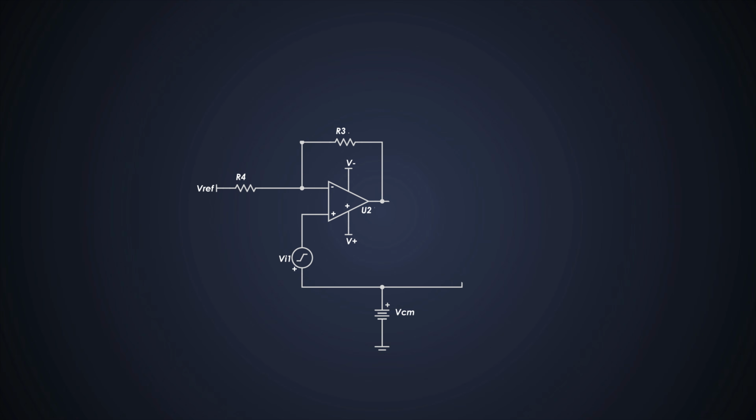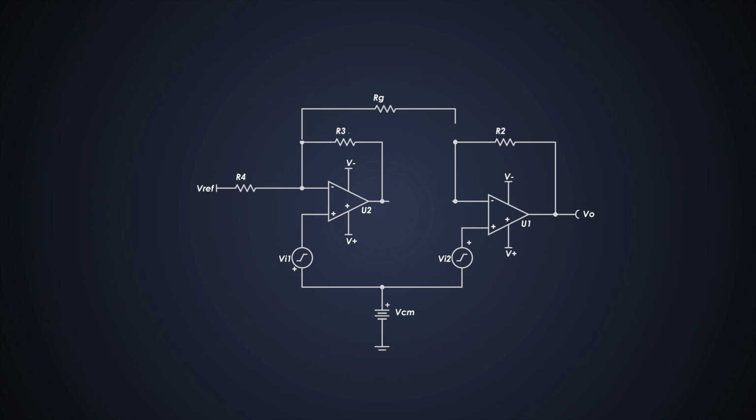It is made up of a non-inverting amplifier and a differential amplifier with negative feedbacks. Apart from that, we'll use one more feedback from the input of the second op-amp to the inverting terminal of the first op-amp. And this resistor is very important because it sets the gain of the amplifier. And here we add one resistor between the two amplifiers.